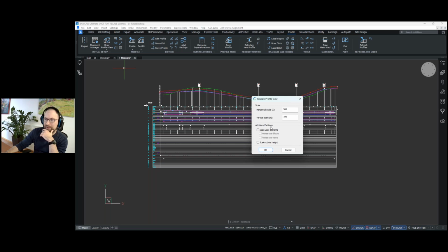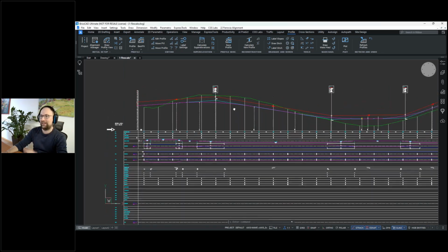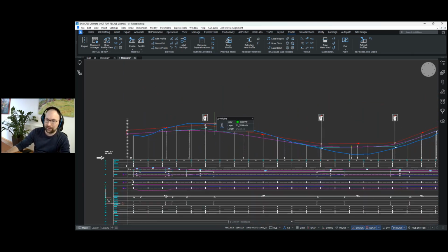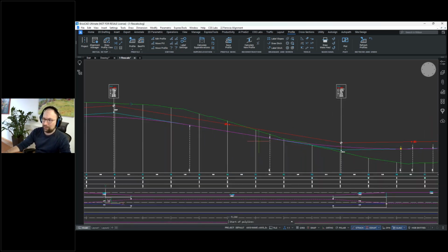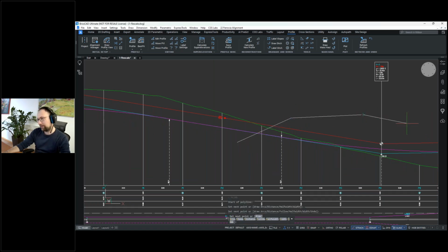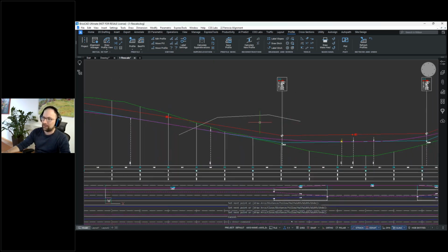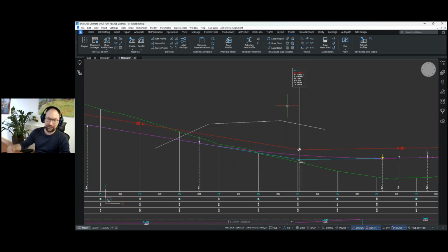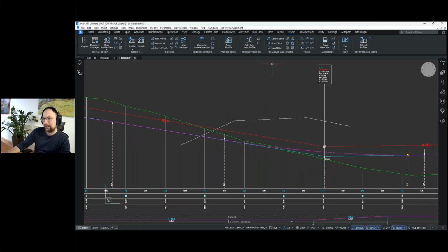With the additional settings, we also have an option to scale user elements. This means any polylines or circles, blocks, hatches, or other things that the user draws in the profile view, for example something like this, and that is not created by the CGS commands in Plateia, Ferrovia, or Aquaterra.